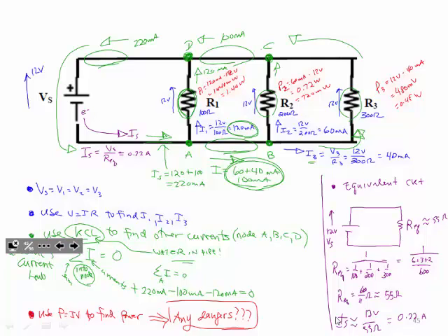All right. So that seems to be working. Now, I also calculated power on each one of these things. So we're on resistor 1 right now. The power I calculated was 1,440 milliwatts or 1.44 watts. What are these resistors rated for? A quarter of a watt, 250 milliwatts. So are we safe or not? Or is this dangerous, what we're doing here? Yeah, we're supposed to be running this at 250 milliwatts or below. So we are almost 6 times above its rating.